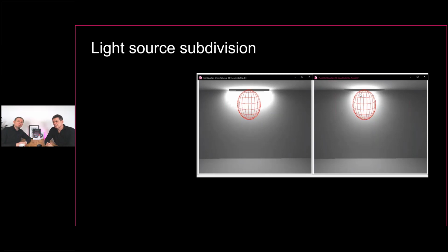Yes. So this is a method where a larger surface of a light output of a luminaire can be simulated, not as a point. So we can here simulate more of the surface of the luminaire. We divide the main point LDC into multiple parts and put the same LDC on each, and reduce the luminous flux so that it fits in total.